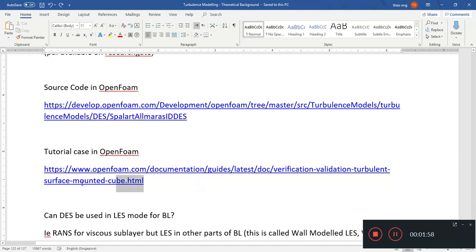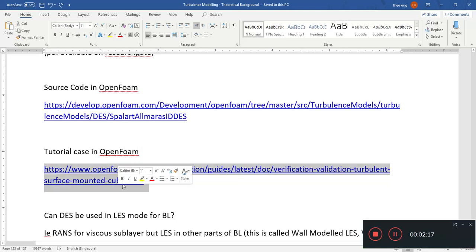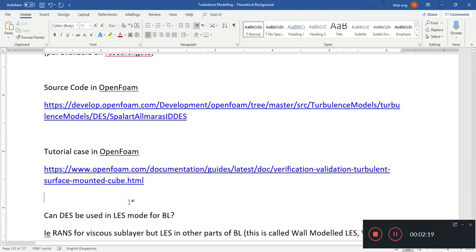And last but not least, a tutorial case is available in OpenFOAM v1812, inside the validation of turbulence, the surface mounted cube. This is the link for it. You can go and take a look. It uses the Spalart-Allmaras IDDES model.